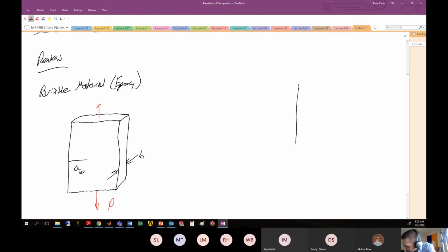All right. So your typical load displacement for a linear elastic material is going to look like this, where you have displacement on the x-axis and you have load on the y-axis. This guy is going to load. And then at some point, it's had all it can stand, and then the crack will propagate inside of the material to relieve the energy that you have put into the material through this external force. So it relieves that energy by fracturing and relieving that load.